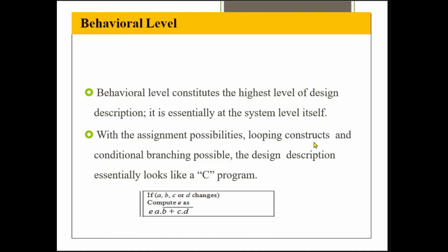For writing simple programs, we can use data flow modeling, but when the program complexity increases, for example when repetitive operations are required, then we can go for behavioral modeling. Here we can include looping constructs and branching, just like in C programming.